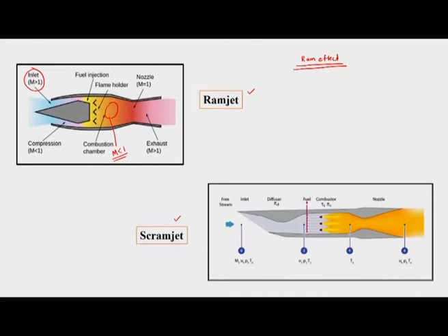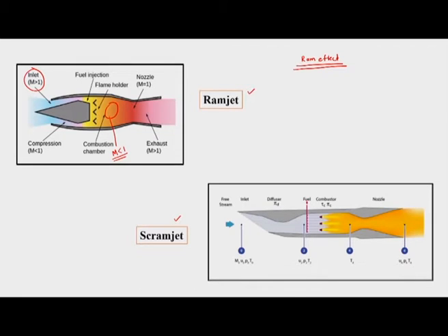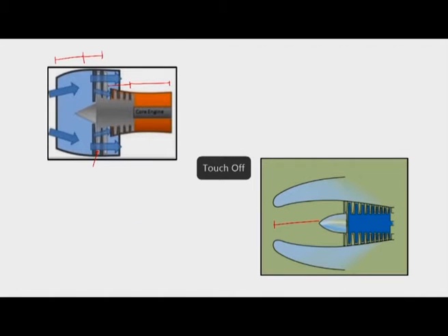If we go into the details of gas dynamics, we would come to know that there will be a shock sitting in front of the intake, and that compression, which is not mechanical compression but thermodynamic compression, would lead to a rise in pressure instead of having a compressor. So, we take advantage of the supersonic flow regime for raising the pressure in the design of the intake. However, if we go back and see, in these cases the flow is subsonic, where Mach number